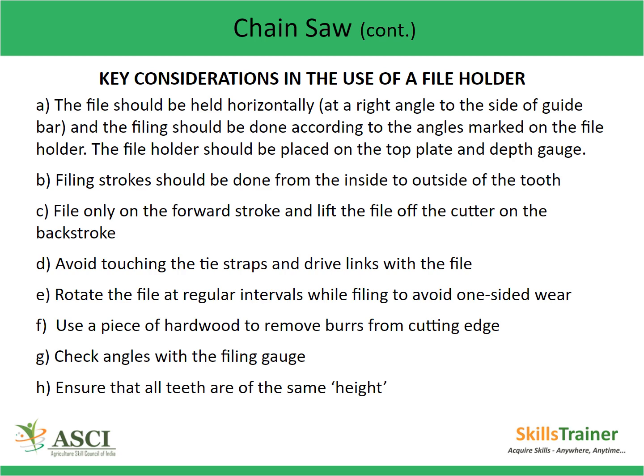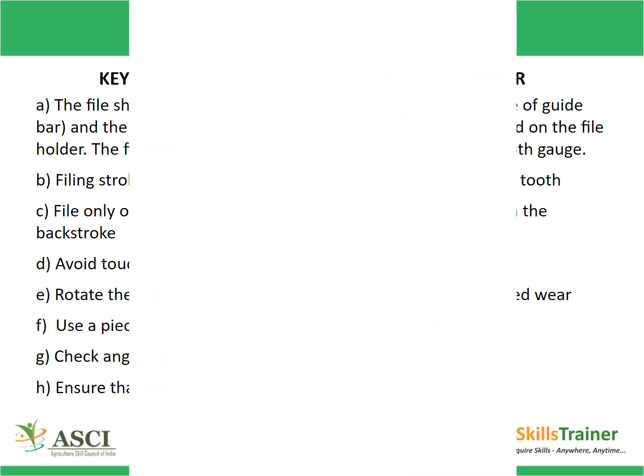Rotate the file at regular intervals while filing to avoid any one side wear. Use a piece of hardwood to remove burrs from cutting edge. Check angles with the filing gauge. Ensure that all teeth are of the same height.